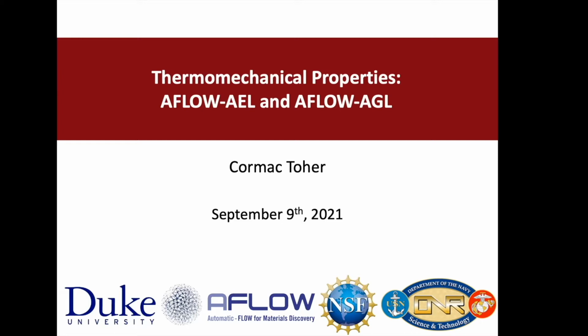This is how you can calculate thermomechanical properties with AFLOW using the AFLOW-AEL and AFLOW-AGL modules. This is the AFLOW-AEL, the automatic elasticity library, and this is the automatic Gibbs library. This one is a Debye-Grüneisen model, and this one is for elastic constants.